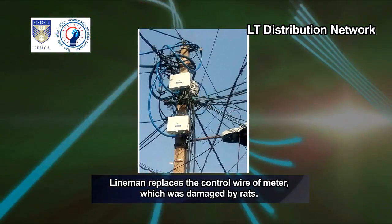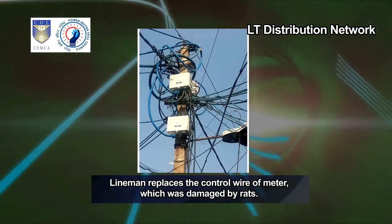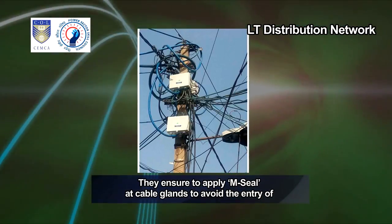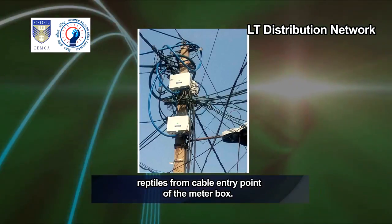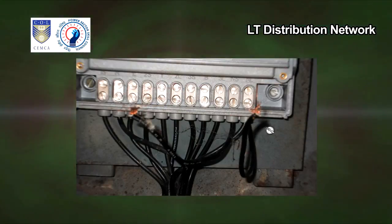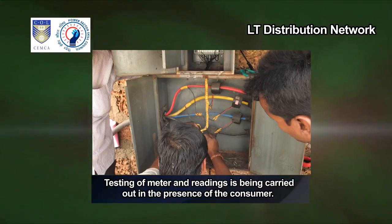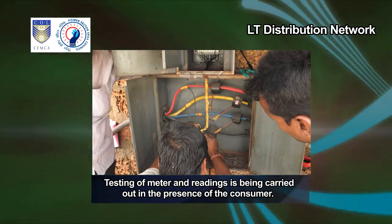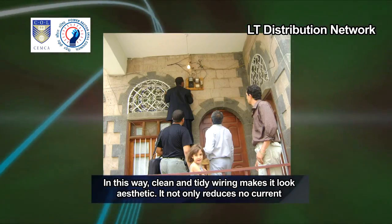Lineman replaces the control wire of meter, which was damaged by rats. They ensure to apply M-seal at cable glands to avoid the entry of reptiles from cable entry point of the meter box. The consumer supply is restored. Testing of meter and readings is being carried out in the presence of the consumer. In this way, clean and tidy wiring makes it look aesthetic.